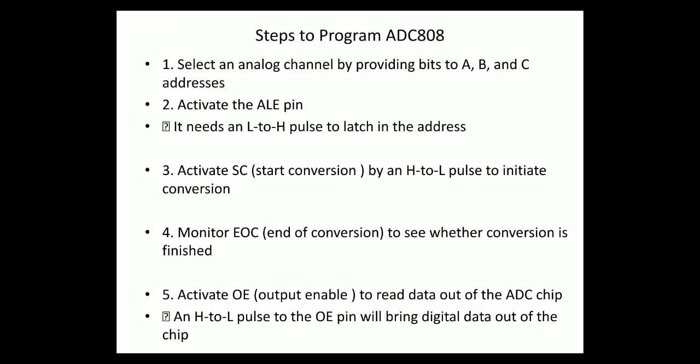Please remember this. I need to only check whether EOC is finished or not. Fifth step, activate OE, that is output enable, to read data out of the ADC chip. OE to read the data from the chip will happen after EOC is done.